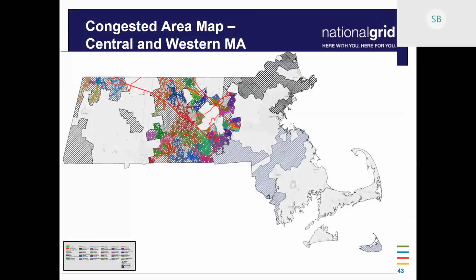To reiterate, where it started was that we got really high volumes of DG penetrations in very targeted areas. It prompted the need for a different voltage class distribution, which means new substation transformers, rebuilding substations, retiring certain substations and replacing them with new ones, or altogether just adding new substations to the area to support all the DG.